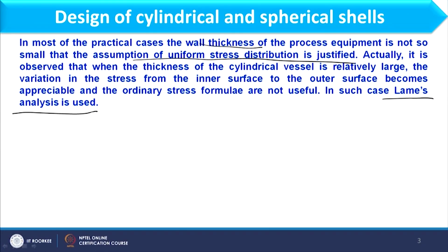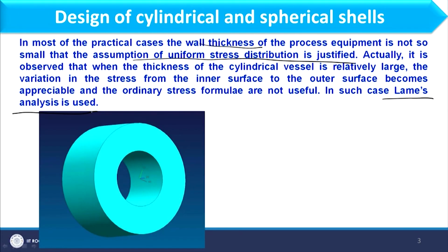So here I have the thick walled vessel, where if you consider this is the total thickness of the vessel, and if I consider stress at this point as well as at this point, stress will vary from inner surface to outer surface, and that we need to consider in designing.